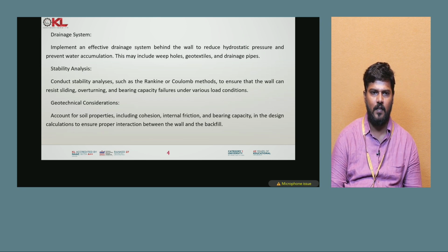Next one is the stability analysis. Conduct stability analysis such as Rankine or Coulomb methods to ensure that the wall can resist sliding, overturning, and bearing capacity failures under various load conditions.